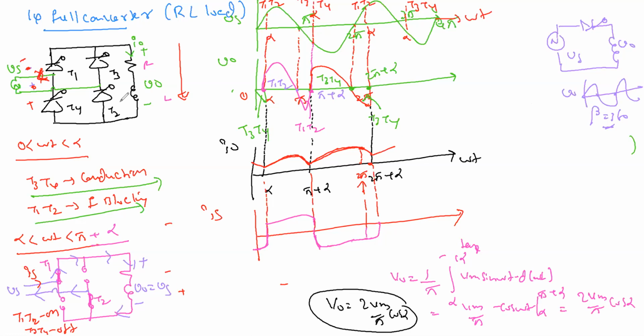Now with the RL freewheeling diode, that's what I'm saying here now. Its voltage is going negative. When the voltage goes negative, the average voltage will decrease. So what should I do here now? Yes, that's correct, Sahu, that's correct. So we will use a freewheeling diode, because with the freewheeling diode there should be no negative output. This negative peak, we have already discussed when the diode is there. Now it's just about the SCR. So with the freewheeling diode, we get only positive voltage here, no negative voltage here now.